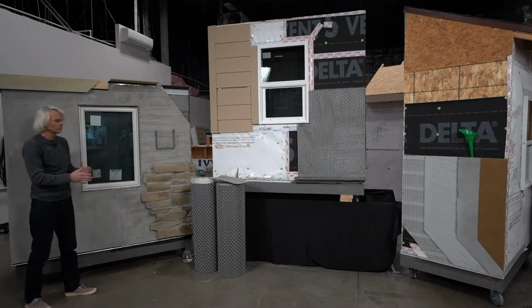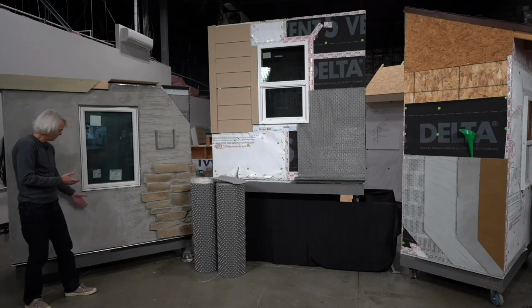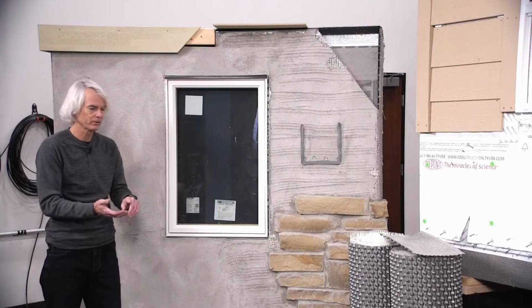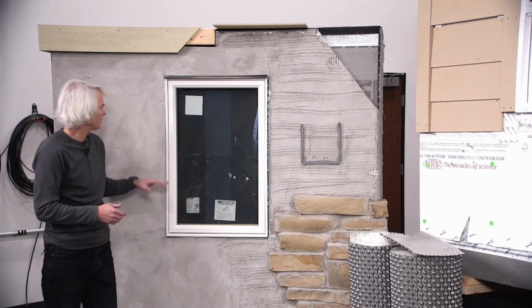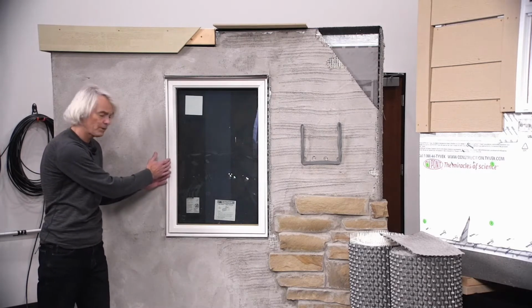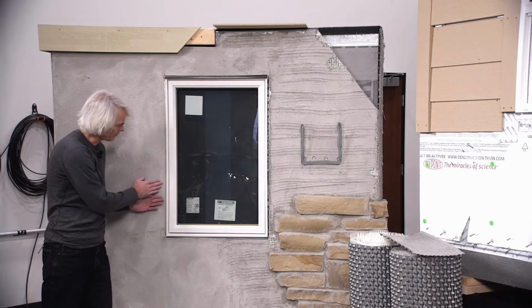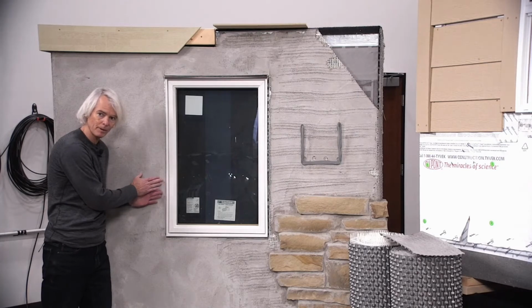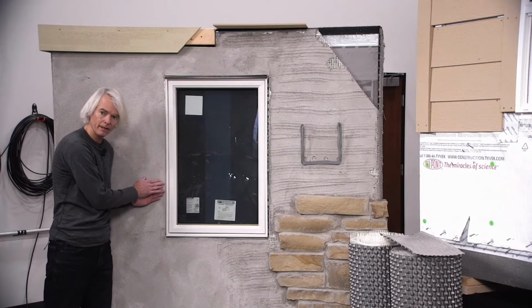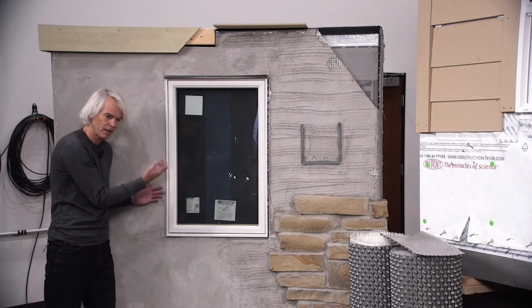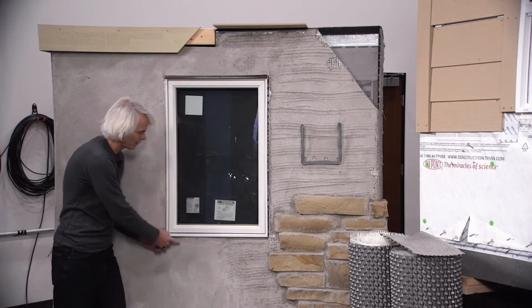Most of the exact same details that we did in the first assembly have been pulled off here with just standard metal drip flashing at the bottom, diverter flashing, and then the weep screed at the bottom of the wall. A few things to point out on these details. Number one is, when we look at the interface between the stucco or even the scratch coat to where the window is, we've held that masonry material off by about 1/4 of an inch by installing a casing bead or a J flashing all the way around this window.